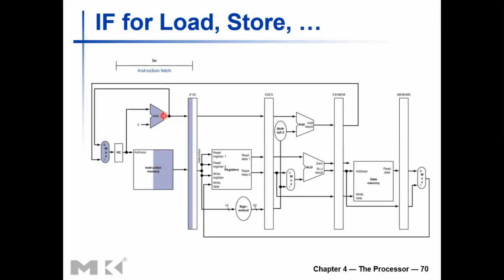So these two pieces of hardware work in parallel. The adder will have some combinational delay, and the instruction memory reading is done combinationally or asynchronously, and that will also have some delay. Usually, the instruction memory has the larger delay. Reading memory has the larger delay.